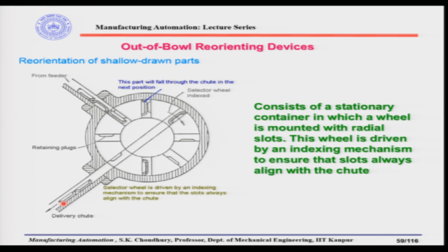All right. Now, when from the feeder the parts are coming either with this orientation, that is the open side up, or with the open side down, they will be coming here and they will fit into this protrusion if they are coming with the open side up. So, open side up will go in and there is a protrusion here, and when it is rotating like this, it will come through here, and it will be retained here, it will not go down, because as you understand, this has climbed here, this is in the protrusion.